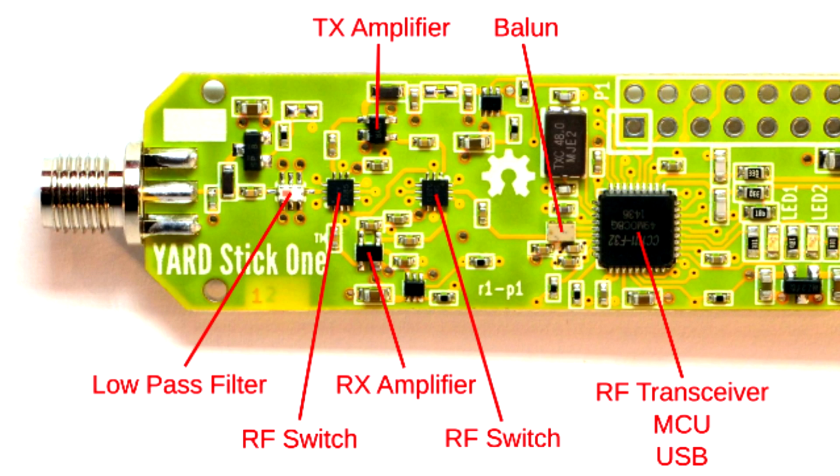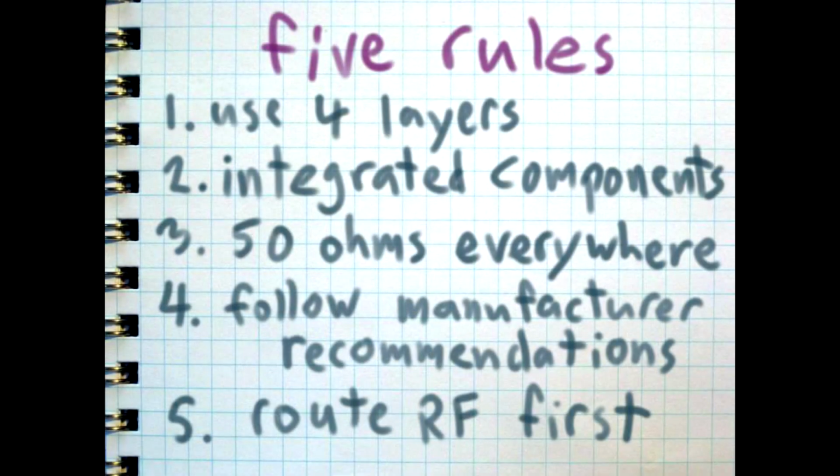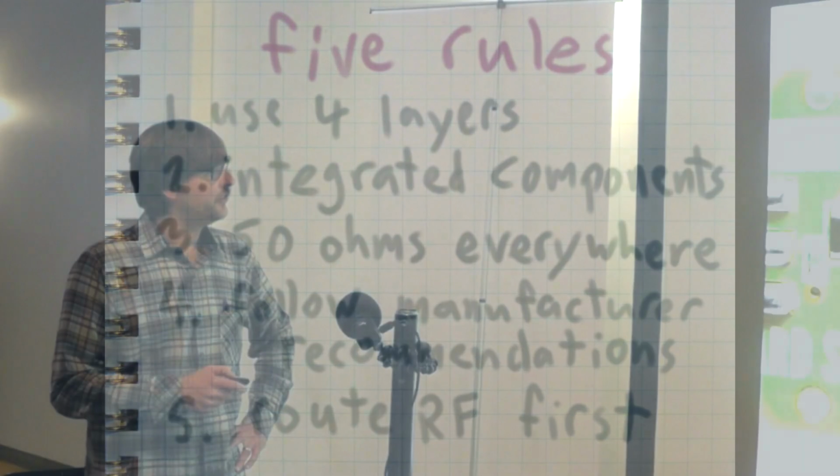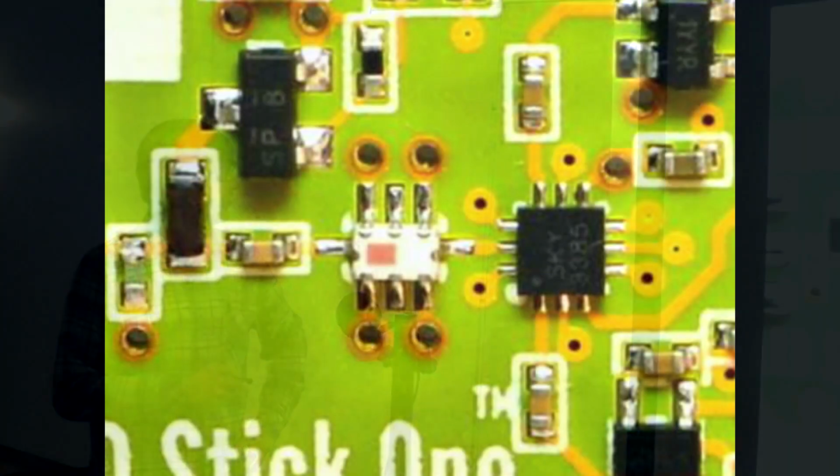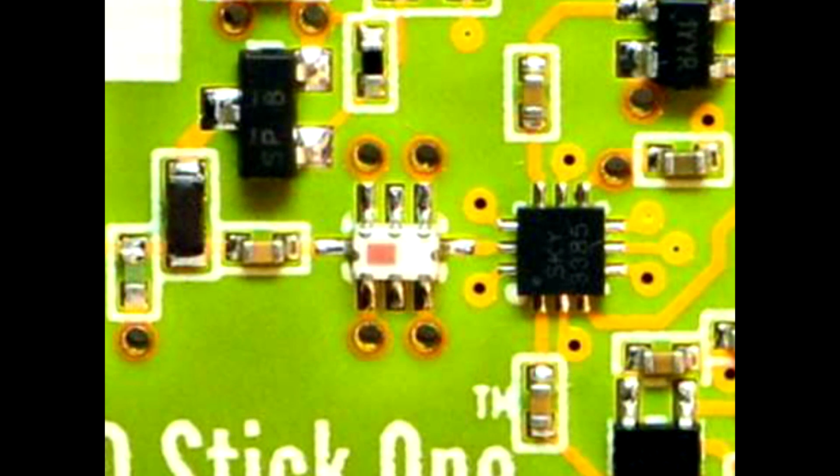It's a lot more went into the design, but realize that every single component follows the rules that I was talking about all along. I have 50 ohm interfaces between everything, and I have as much integration as I can, and so forth. Now, on the other end here of this switch, we have, see this thing? Looks kind of like a balun that we've seen before. It's not a balun because it's single-ended in, single-ended out. It's actually bidirectional, so which one is in and out is kind of up to you.